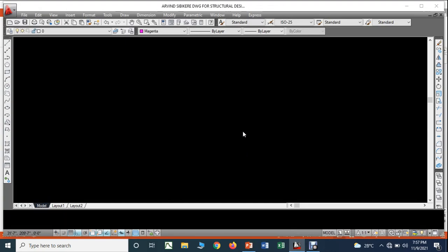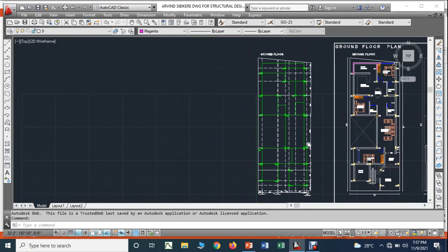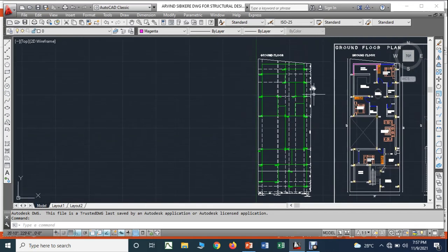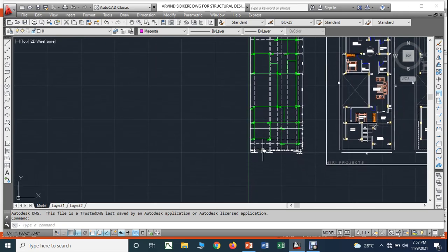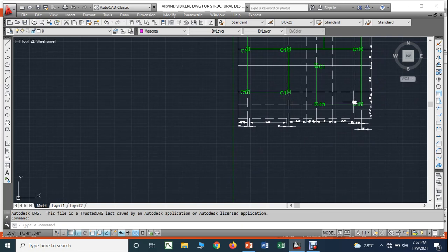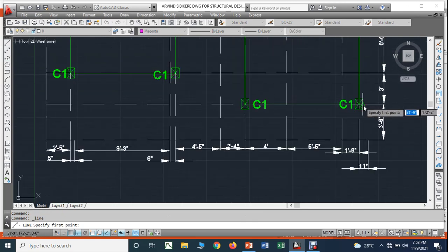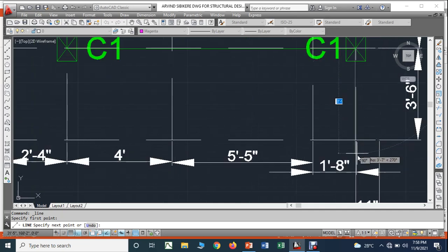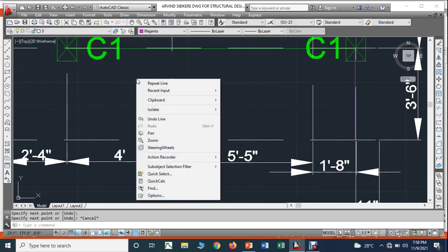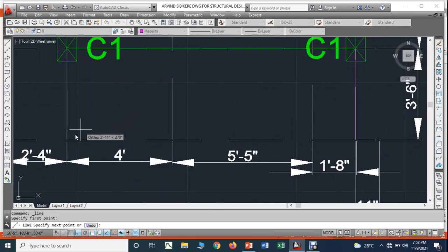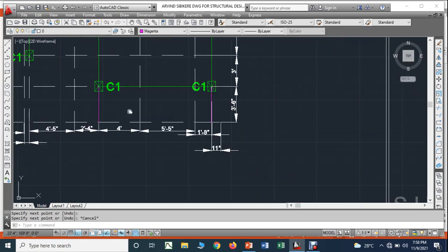Now, as a continuation, in this video you can see I have prepared the complete positions of the beams and columns of the ground floor. Here I would like to make a small change, that here we have 4 cantilever beams. As per the architectural plan, the cantilever beam starts from here to here because this is our boundary line. So this is my cantilever beam, and next from here to here is my cantilever beam.